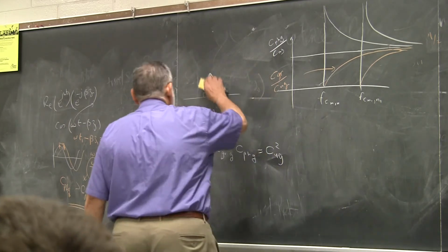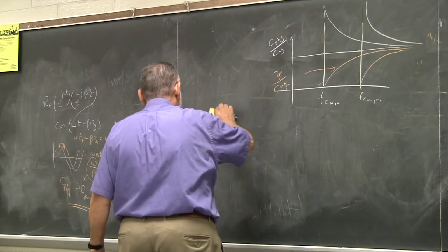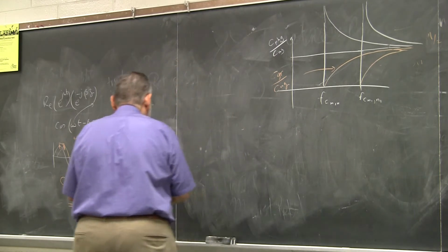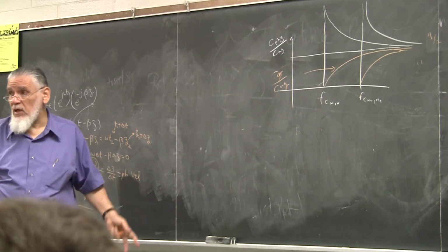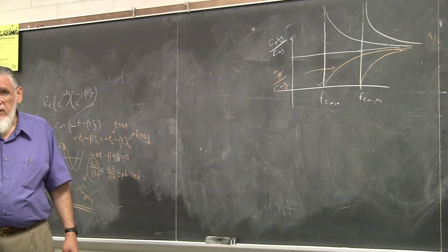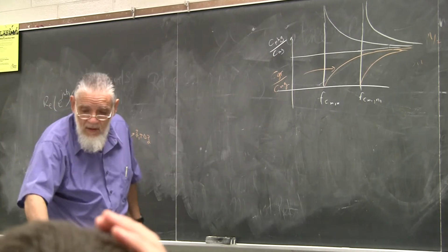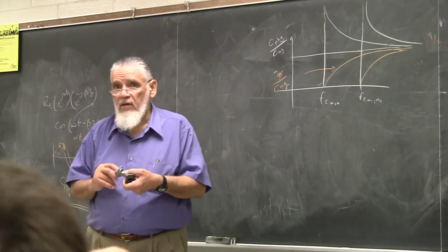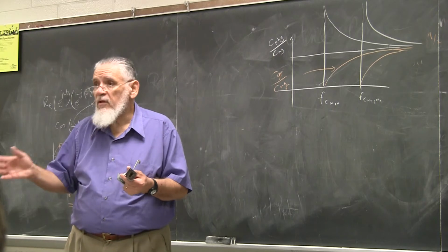If we go to the practical situation and start introducing the losses in the guide. Because so far what we've done was assume that the guide was lossless. We assumed ideal conductor, we assumed ideal dielectric. The reality of the matter is that you have some losses. Basically, you have surface currents because of the finite conductivity of the metal, let alone the dielectric losses.